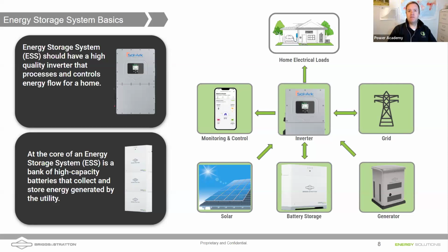Another can be inverter clipping. When I sold solar, I was a power dealer for a long time. We would have a Maxeon panel, maybe a 400-watt panel, but the IQ7 or IQ7 Plus microinverter might only be able to do 320 or maybe 340 watts, which is acceptable to have some inverter clipping.